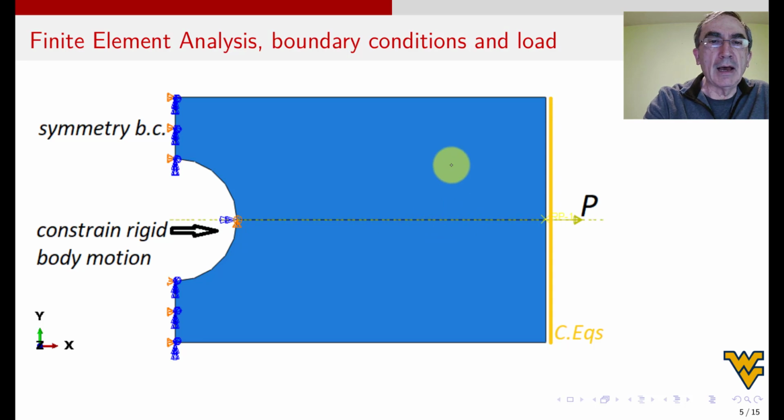So I model one half. Then I have to put the load. Now, if you put the load at one point, which in FEA will be called a node, then you're going to get a stress concentration here, which is not real because you're never going to apply the load like that to a real structure, just at one point. And so the load somehow is going to be applied in practice, distributed over this region to make it more or less uniform, all right?